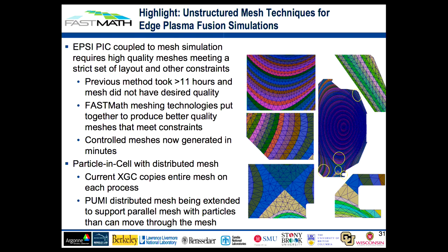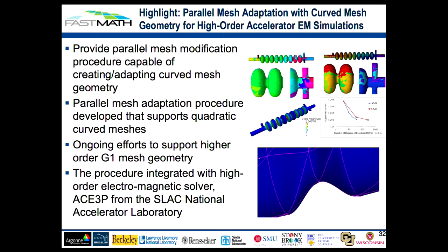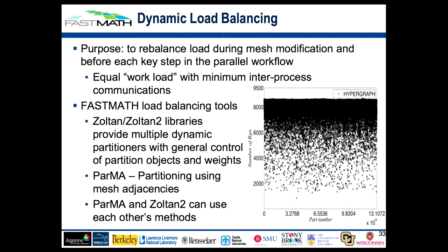We're also doing this in a PIC code in which we're providing very specialized mesh generation capabilities that are field following for these magnetic flux fields, and have basically taken their mesh generation process, something that was exceedingly painful, down to something that's now automatic and in a matter of a few minutes just to set up the mesh control parameters for new reactor geometries, etc. I mentioned we do the higher order meshes. This is an electromagnetics code from SLAC in which they are dealing with curved finite elements, and we generate and adapt those meshes for them.